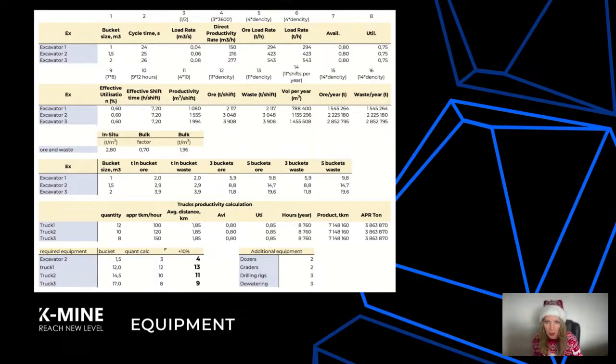One approach is to start by selecting a range of excavators, each with unique features suitable for the required rock mass removal from the pit. We input these specific parameters into our calculation model to identify the best fit. Sometimes the strategy is reversed, especially when the goal is to expedite the pit development and increase production. In such cases, more productive excavators and dump trucks are needed, depending on what the limiting factor or bottleneck is. So we've chosen 3 models with smaller buckets, and as we don't really need high output here, the key for us is working efficiently.